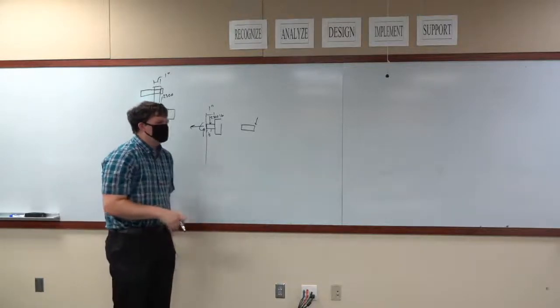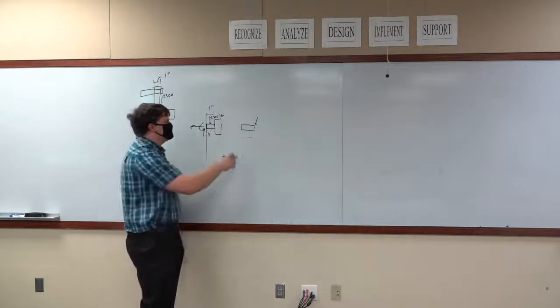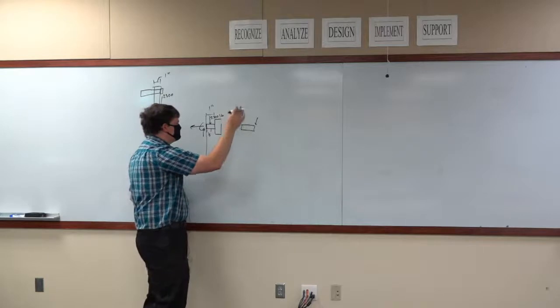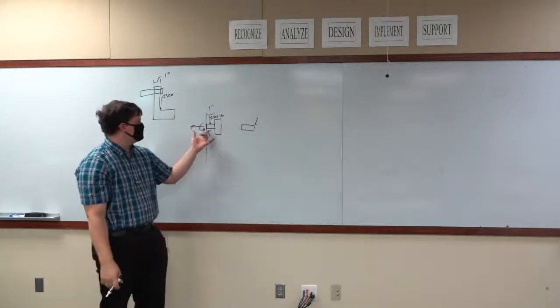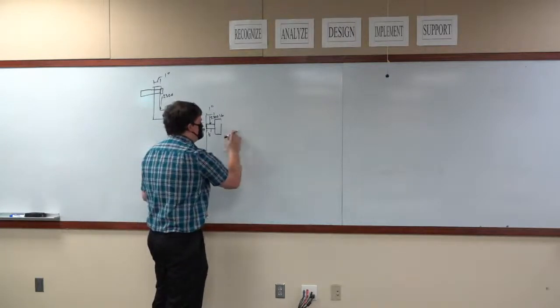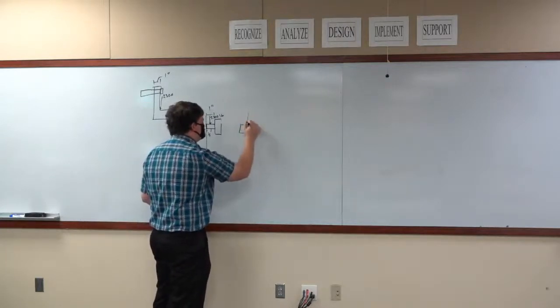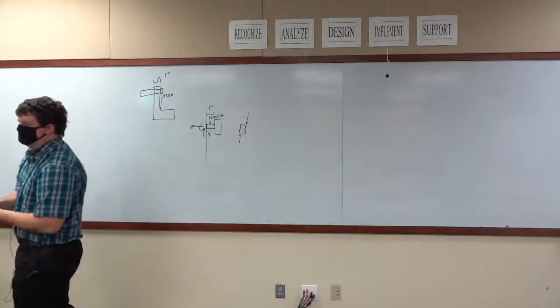You're not really going to be seeing any deformation out of this bolt in this half inch. You can basically treat this as if you're carrying a shear load, 2,300 pounds, and no moment.